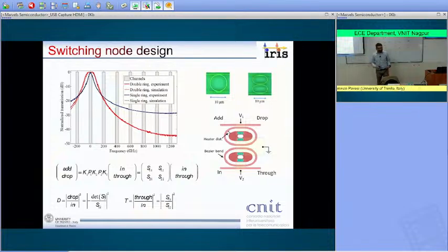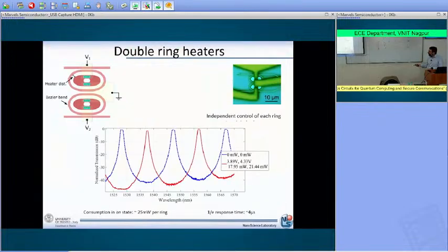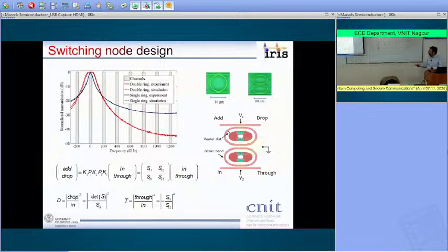So in order to increase the rejection rate, so in order to decrease the quantity that adjacent channels, different wavelength channels, are affecting the proper channel that we are addressing, what we ended up with was a sequence of two micro-ring resonators.